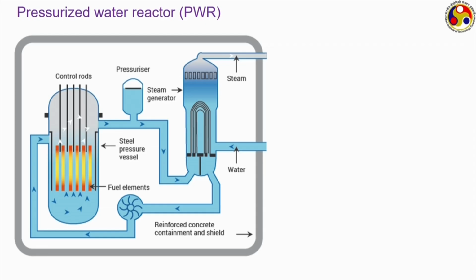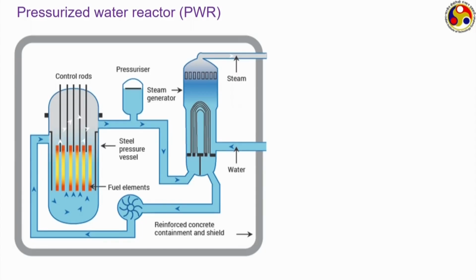It was mentioned in the previous lecture, a previous module, that in PWR the control rods are inserted from the top, and hence the control rod connecting mechanism or driving mechanism, particularly the spider, is mounted at the top of this pressure vessel. And these fuel elements and also the control rods are completely immersed in the moderator, and the moderator in this case is water, that is, only liquid water. No phase change is allowed in a pressurized water reactor, and the water that we are using as coolant and moderator must remain as single phase liquid in order to operate a pressurized water reactor.